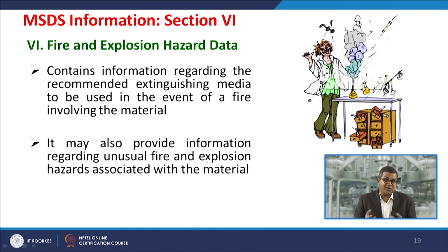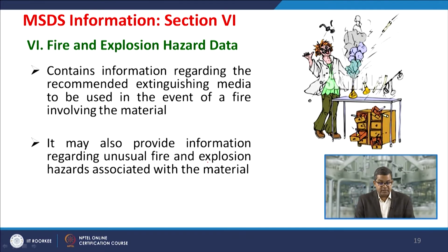This contains the information regarding the recommended extinguishing media to be used in the event of a fire involving the material, because you cannot use a water based fire extinguisher in case of electrical fire, or if by any means cooking oil catches fire, then you cannot use water as an extinguishing media. So you must know which kind of fire extinguisher is used in case of any fire. This particular section may also provide information regarding unusual fire and explosion hazards associated with the material.